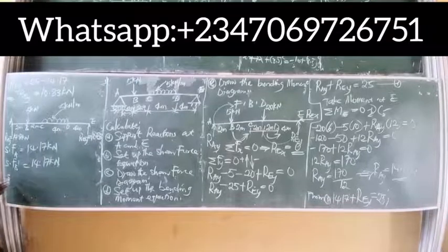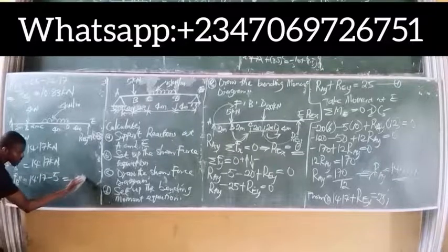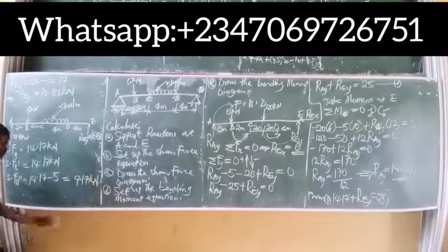So we simply have the shear force B prime prime, which means finally at point B, this force 14.17 kilonewtons now encounters a downward force of what? 5, which is simply minus 5. What is now the value? 9.17 kilonewtons. So this becomes the shear force at point B.